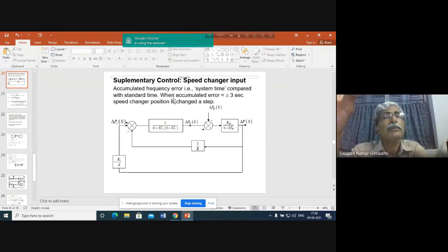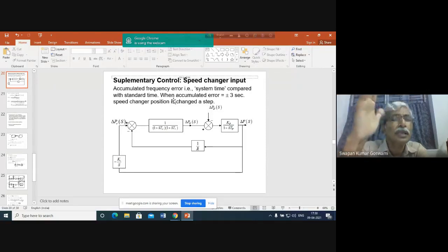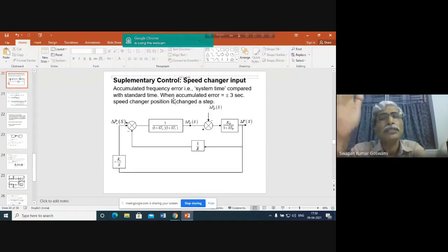Because of this availability based tariff, which was implemented in 2003, frequency has drastically improved in our system. If you see the frequency excursion in our system before 2003 and after 2003, you'll see a huge difference between the two. Previously there was much variation in the frequency, of the order of say 5 Hz.